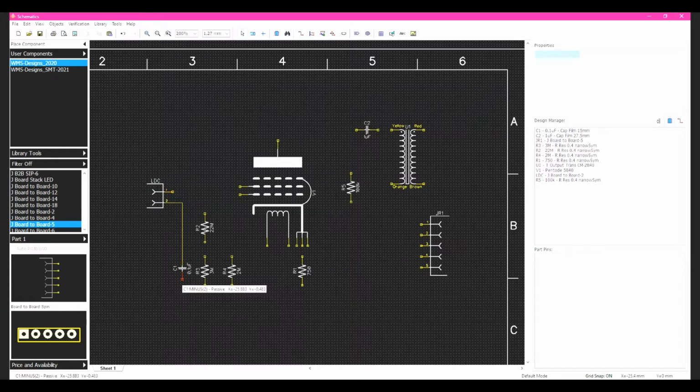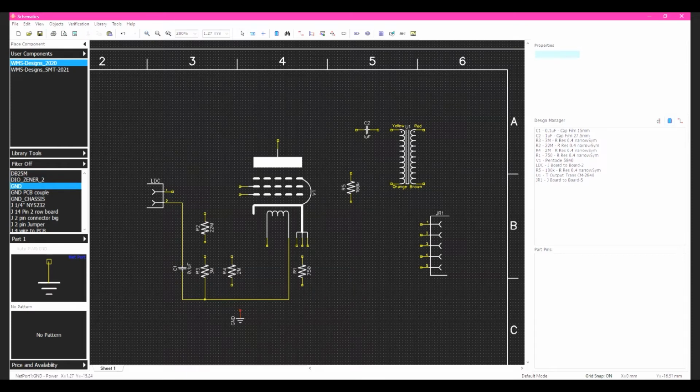So I'm going to start making my connections. Down here, lots of things connect to this bottom area. Not that though. So I'm going to connect here. These two connect, and then that also connects to pin 6 here. And this is actually ground. So I'm going to go ahead and come over here and grab ground. Put my ground symbol there.